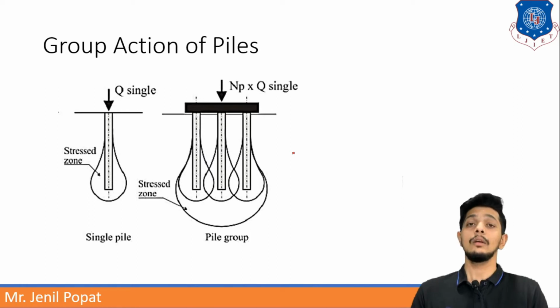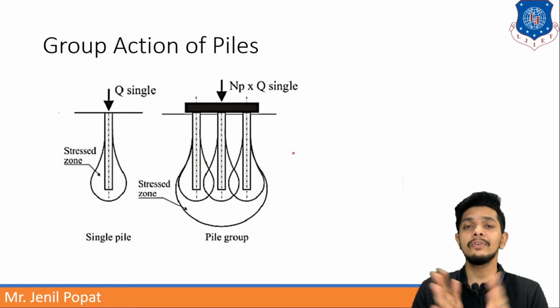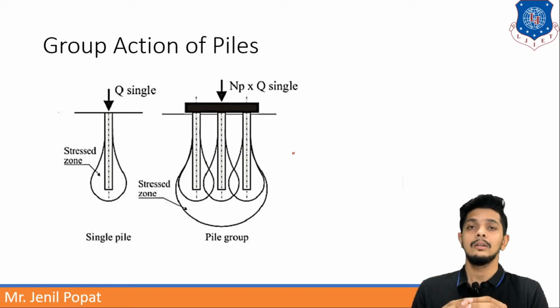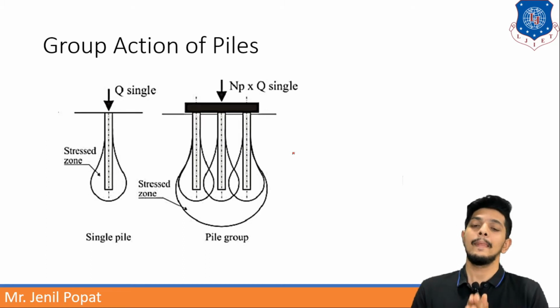The reason behind this is that the soil in between this group of piles is compacted, or fitted in, and due to this interlocking it has more stress area, or more load carrying capacity. So this is the group action of piles.